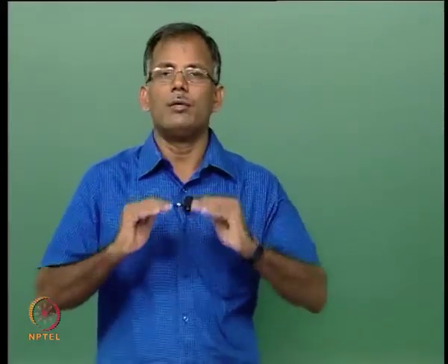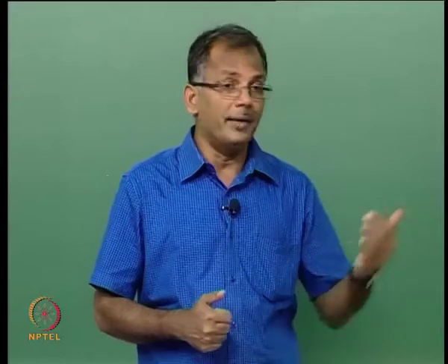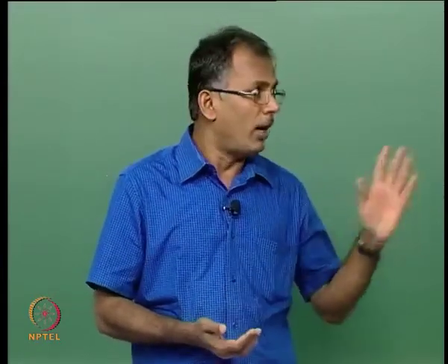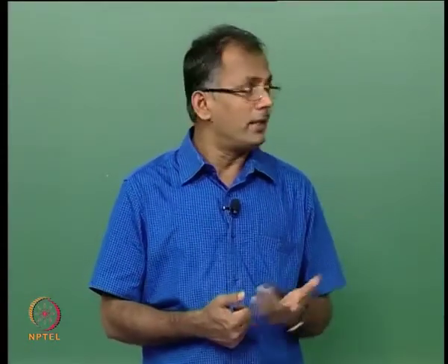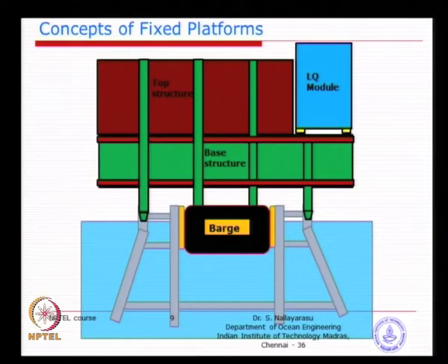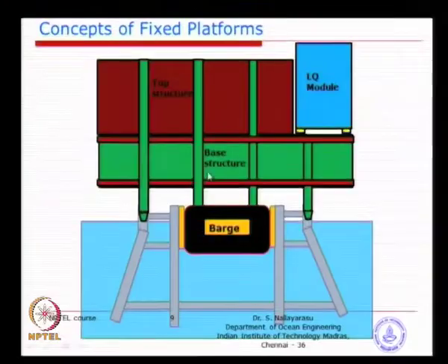During the process, water level may change due to tide. I think most of you might have heard of tidal changes, and then the sea state, because of the wave height, the barge may go up and down, and that may create elevation change. So, while you are ballasting water inside the barge, you are also moving up and down. This may create additional forces, and also what is not shown in the animation is the lateral movement of the barge, which you can see on the sides of the barge.